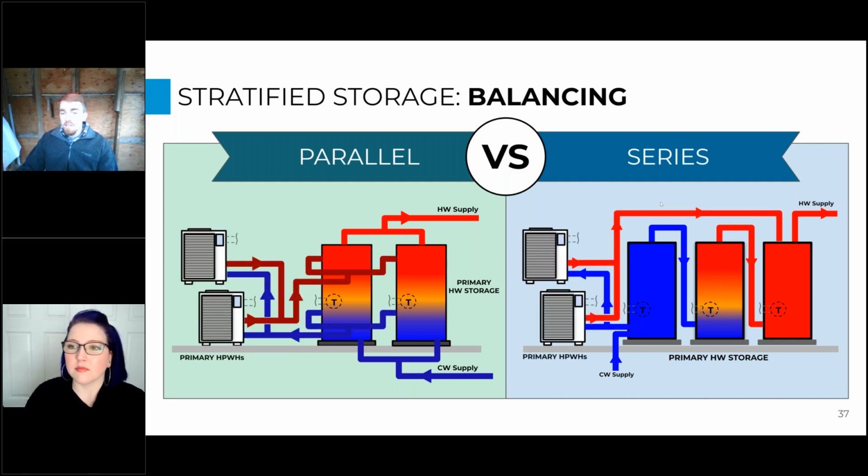Right now, the flow of water is going into the top of the tank, and it's being pulled from the bottom of the tank in series. So now we're filling this top tank with hot water, and we're actually back charging it. And then once this tank is completely full of hot water, that will then work its way to the middle tank, and it will completely charge that middle tank with hot water as the cold water is being pulled out of this line and into the heat pumps.